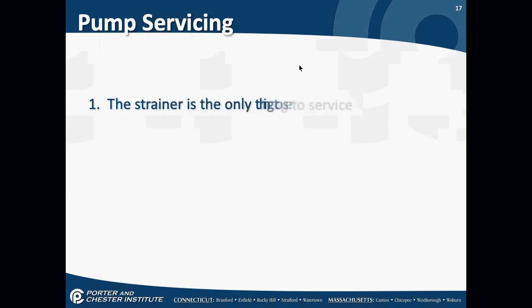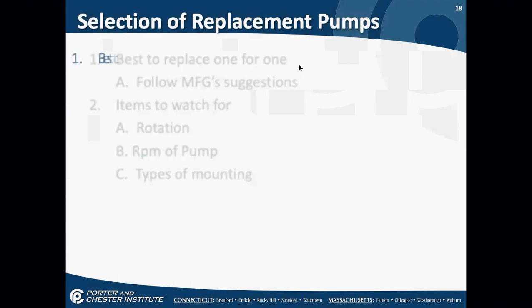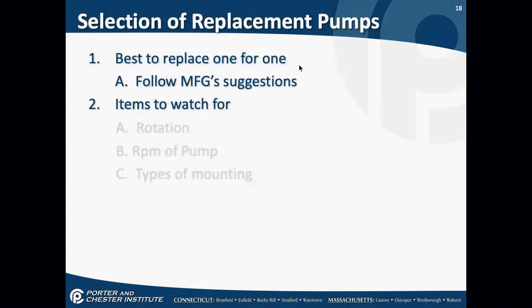There's a strainer in the pump. That's the only thing you can service inside an oil pump. It's the only thing that you can change out. You're not going to rebuild a pump. You're not going to change the gears out. You're not going to change the parts out. The strainer is the only thing you can change out. Other than that, you're going to replace the pump.